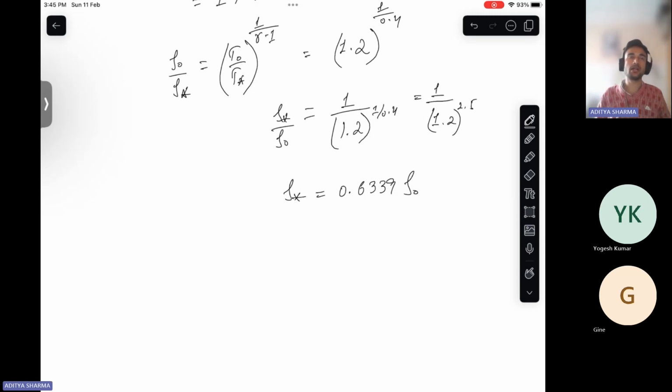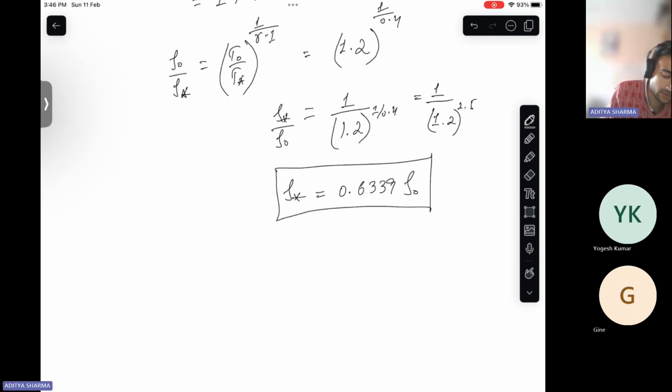So I was saying that at this reservoir, or at the initial condition when there is no flow, at this stagnation condition, static and total are one and the same. But when there is a flow, static and stagnation are not one and the same. So in that case, the static has reduced to this. But we have been asked by how much it has reduced.